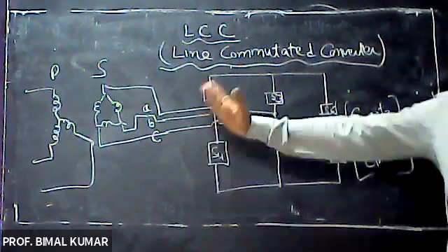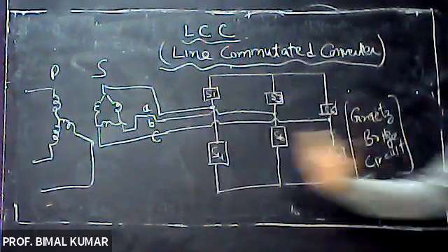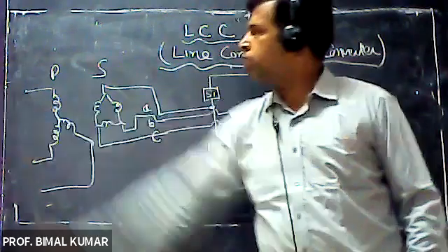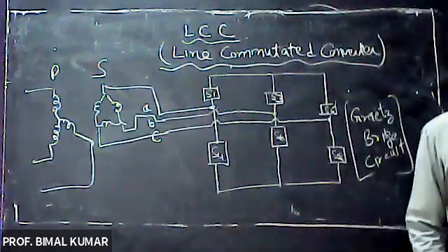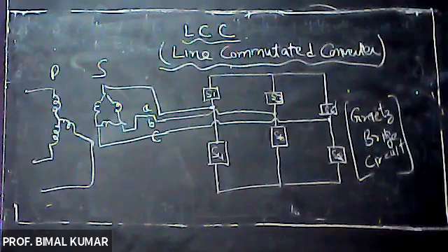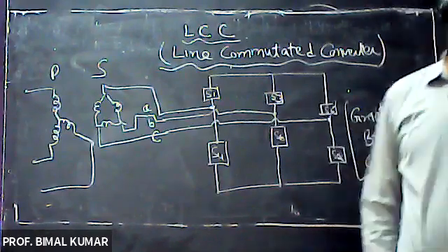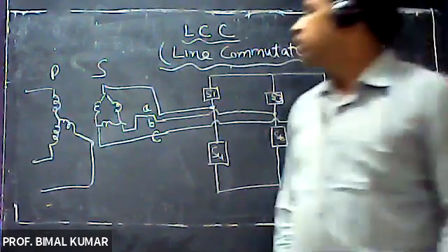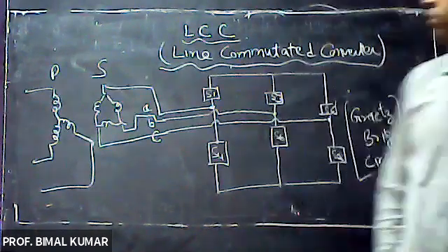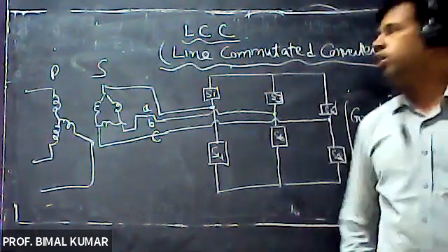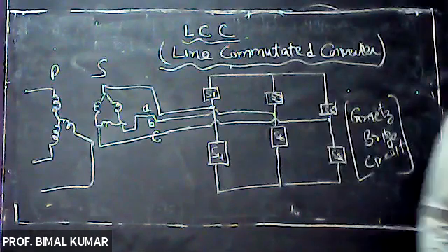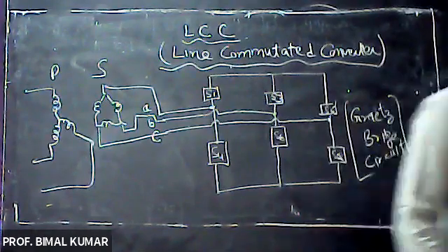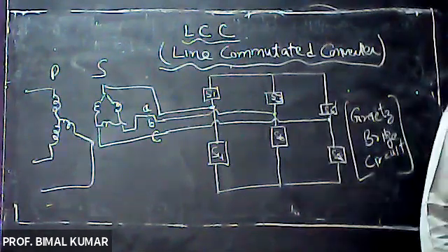Now on this side I am talking about the DC side, and on the input side of this transformer, that will be the AC side. So there is galvanic separation between AC and DC sides, because they are not physically connected with each other.